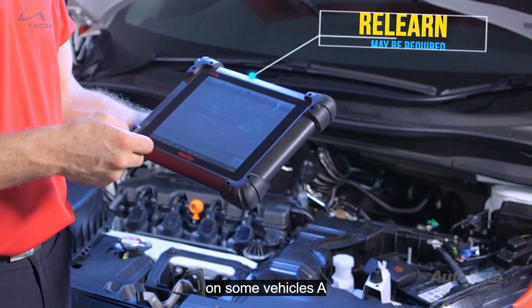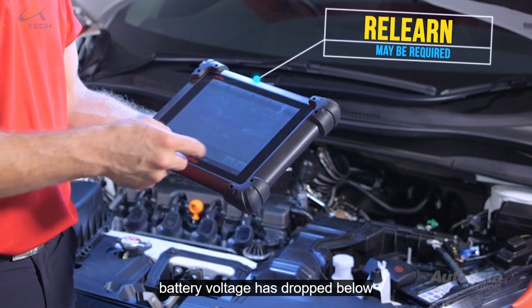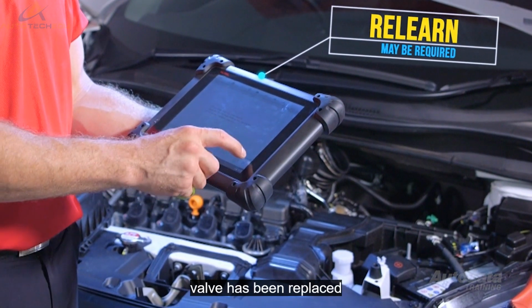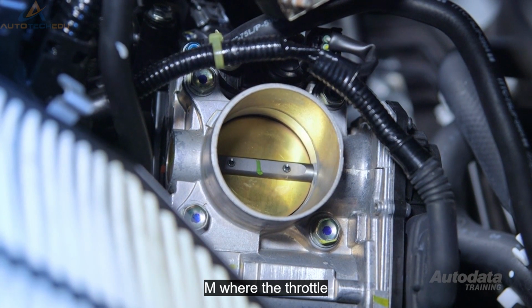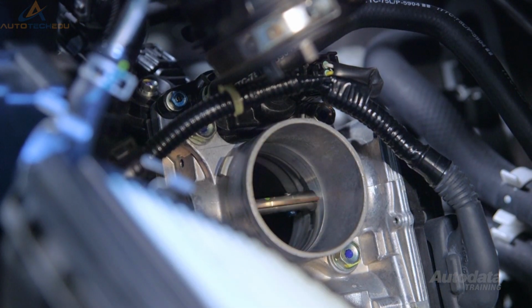On some vehicles, a relearn of the throttle valve assembly may be required if the battery voltage has dropped below the minimum threshold, or the valve has been replaced. A relearn procedure is simply teaching the ECM where the throttle blade sits at idle and wide open throttle.